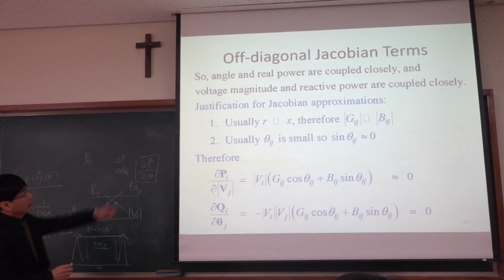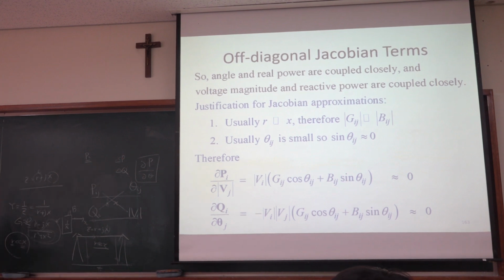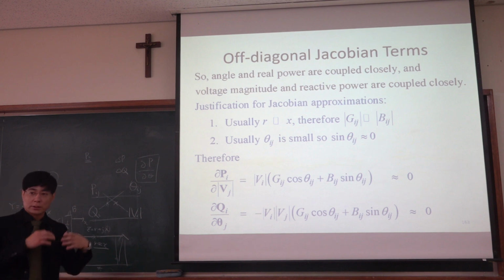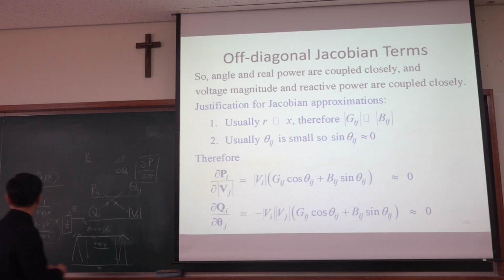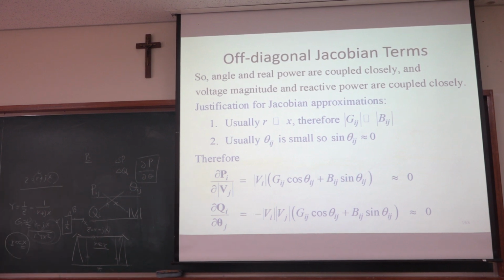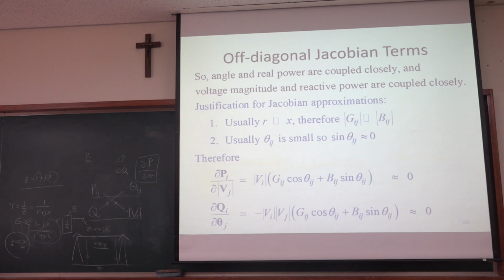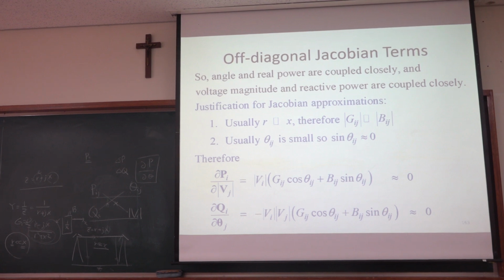The reason is because in this decoupled power flow, we still have reactive power. We still consider reactive power. But in this DC power flow, we completely ignore reactive power. We only focus on active power. Okay, so finally, here the theta is given like this. We only focus on active power and the phase angle. And the admittance matrix and the imaginary part is B. Okay. Good question. Any other questions?